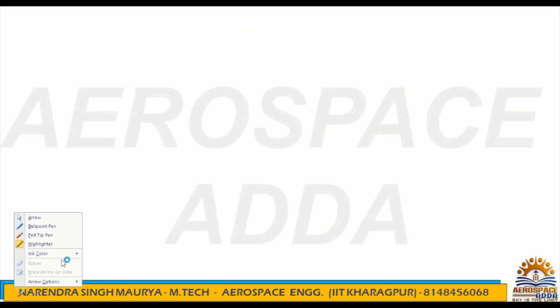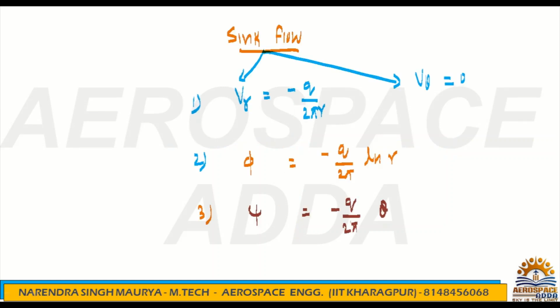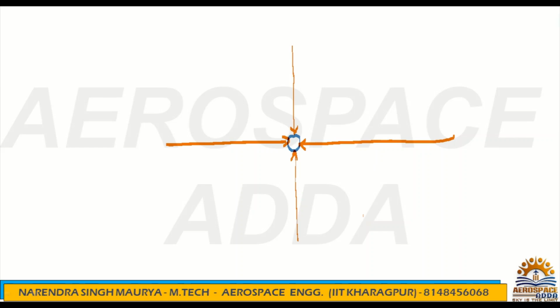If you want to draw the equipotential line, because here it's a circle, there is no issue, you can draw directly. But generally, first you draw the streamlines, and for the sink flow they will be inward, just like this, because it's a sink flow, so all the streamlines will go inward. You already have proved. This is the psi value, so it's minus q upon 2 pi. So the minus sign is indicating just the opposite, and obviously it's a sink, so that flow will be inward.